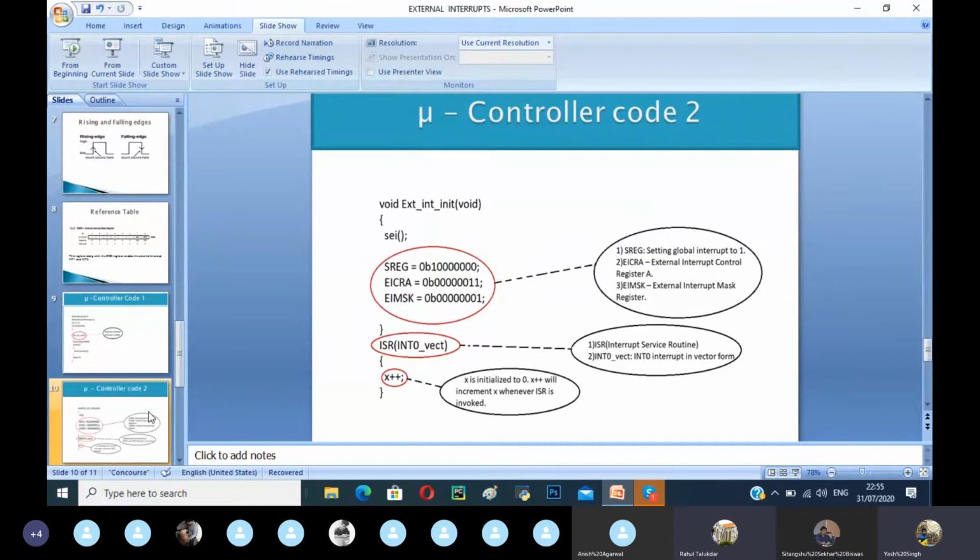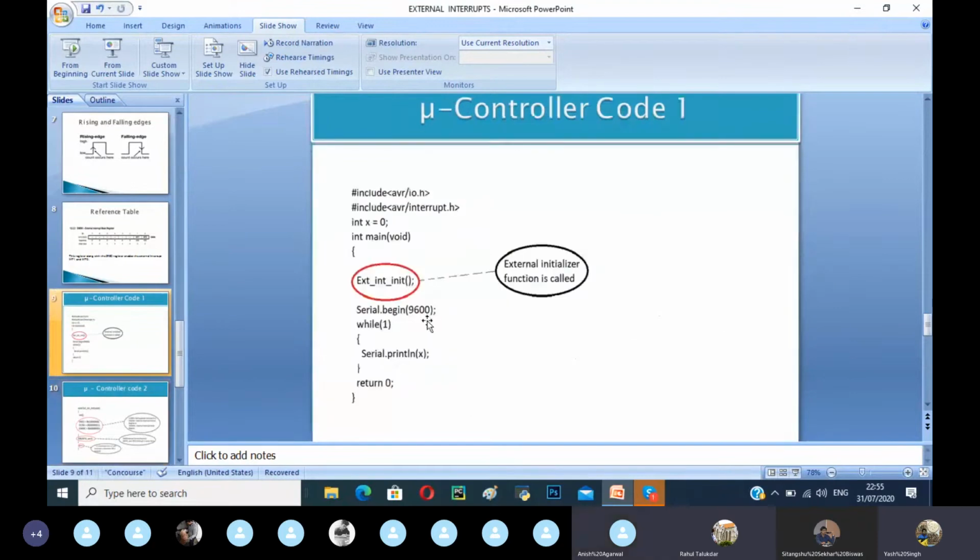We put this command in the infinite while loop because the baud rate is 9600 and it is going very fast. Whenever the value comes once, it would suddenly appear and then disappear. We want it continuous so that we can visualize what the value is. That is why we put it under the infinite while loop.